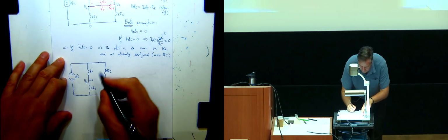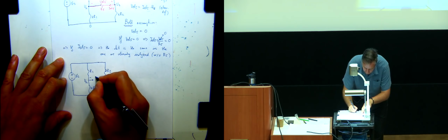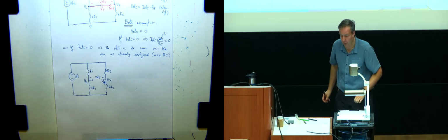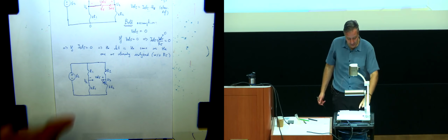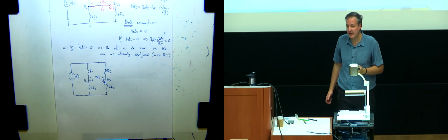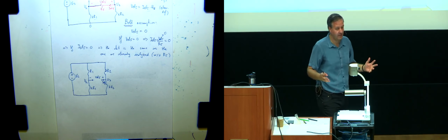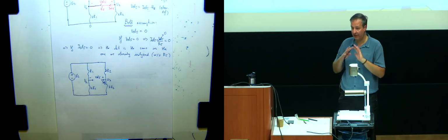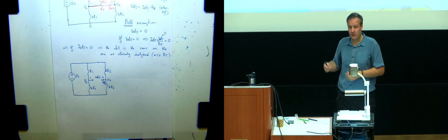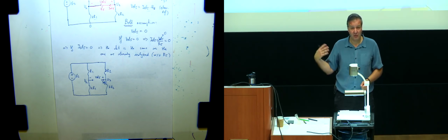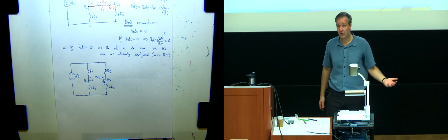So all I'm saying is essentially this. I keep this I element 5. Okay, so what I did, I pulled out resistor 5. These two circuits still need to be equivalent. In what sense? They need to have the same U2 and U3, right? And all the other things, currents through the branches, elements, everything has to be the same, so that these two circuits are equivalent. We're going to talk a lot more about the concept of equivalence later, but essentially, when voltages and currents are the same, circuits are equivalent.